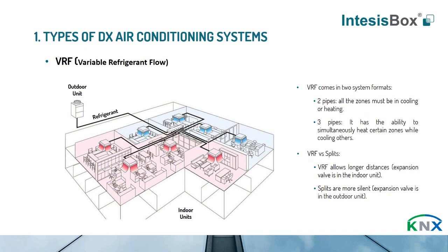This is the reason why the VRF system allows longer distances, and that is why it is usually installed in commercial areas or offices. However, the splits, because the valve is installed in the outdoor unit, are more silent. So that is why this is a system dedicated to domestic use, for homes.